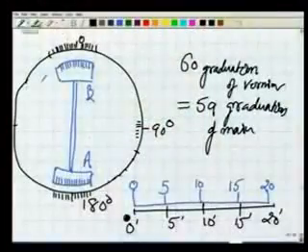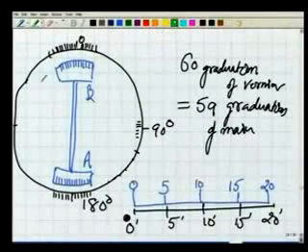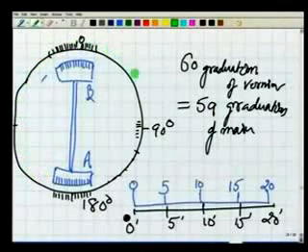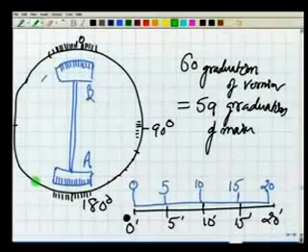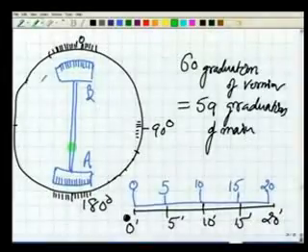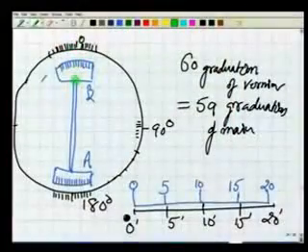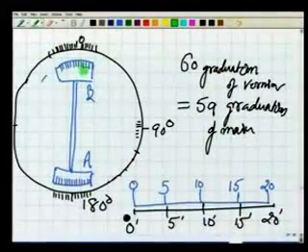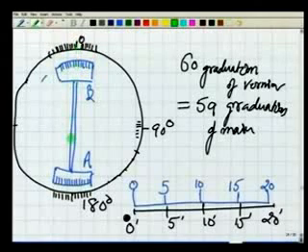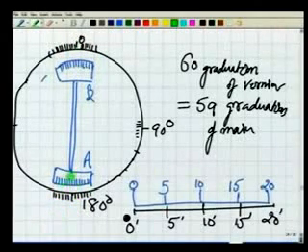As we have seen in the case of the vernier one, this black one is the horizontal circle, or it may be the vertical circle also, and this AB is the index, either in the case of the horizontal circle or the vertical, in any case. What we do is read the angle value against these verniers, to find the value of the reading. How to take these observations, we'll see now.